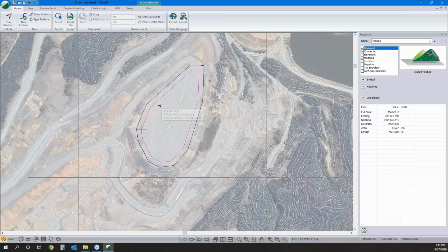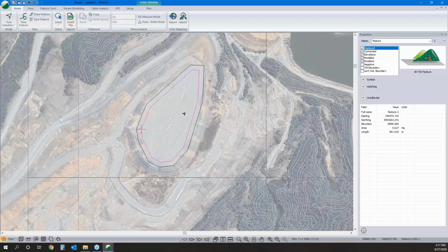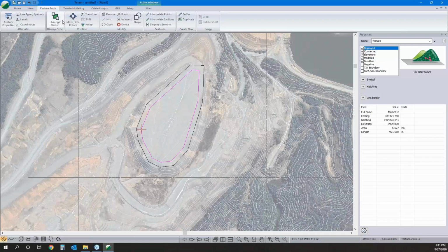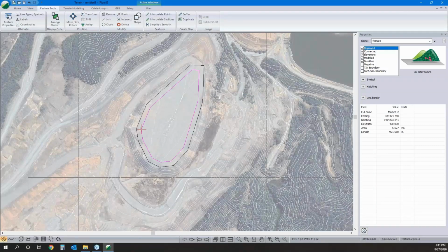All right, so now I'm going to use the grading tool. One thing we'll look at, so I'm just hovering over my background, I can see the tin elevation. So here, my tin elevation is 380. Here, we're 400. So I'm going to change this to include elevations, and I'm going to shift it. So right now my elevation doesn't make any sense, so let's do a quick shift. There, that's up around where it should be.